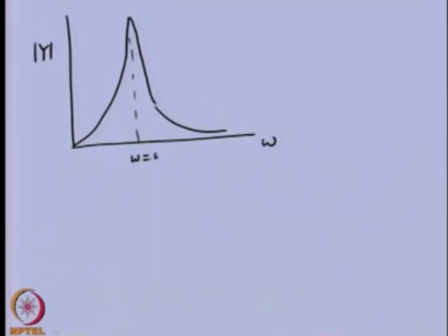Nearly at natural frequency it would be infinite, but as we increase the damping, the maximum will occur slightly below the natural frequency. So, these are for different damping ratios. This is the increasing order of damping. The response would be seen like this. There will not be 0 here at the corners.